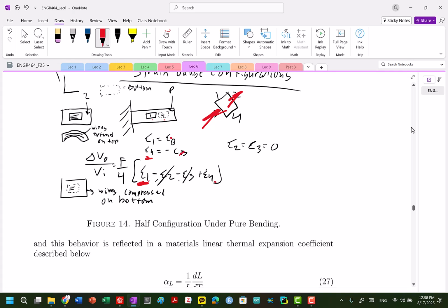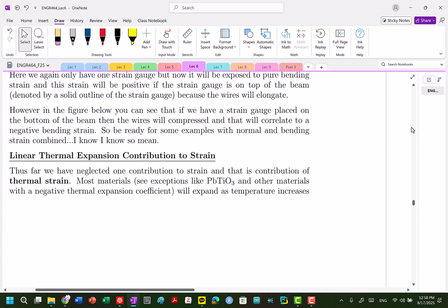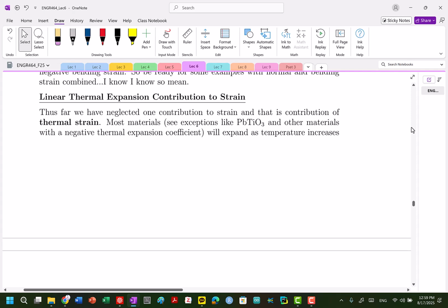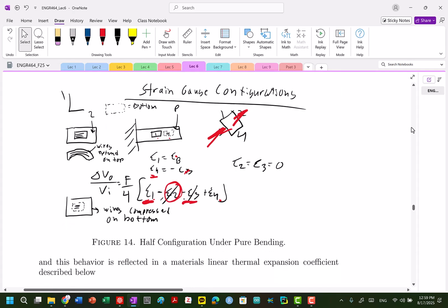So putting the strain gauge in the particular positions really matters. You really have to be aware of that when you're connecting your Wheatstone bridge. You can unintentionally connect the Wheatstone bridge, and I did it in our lab, where you cancel out that voltage and it's not changing. Same thing when you're trying to amplify the signal as well, potentially.